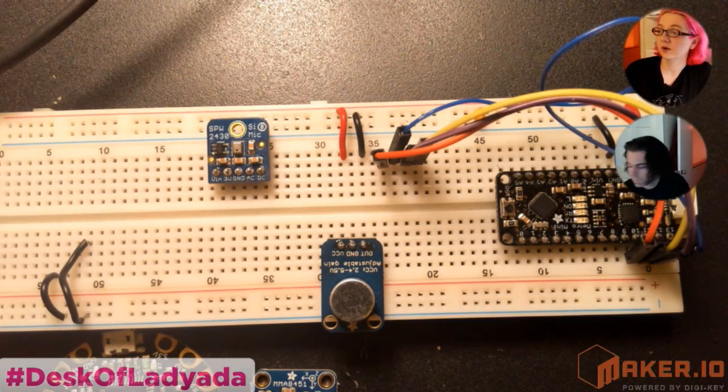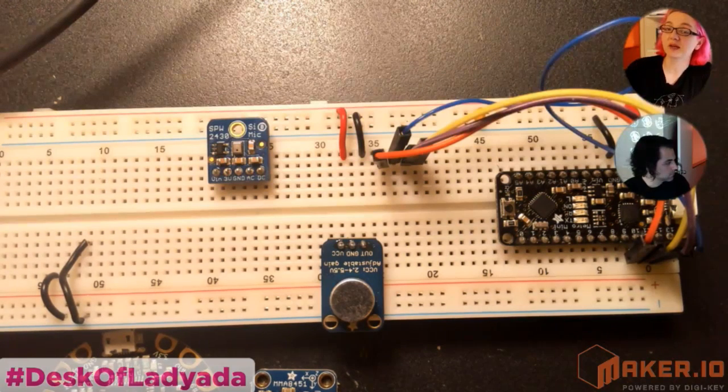Like the Nordic only has one UART bootloader. There's an over-the-air bootloader, so those are their two options. With the ESP8266, the bootloader is built into ROM. You're stuck with that. With the Atmega 324, you can use an Arduino-compatible bootloader, or you could possibly use a Moteino bootloader. As I played with it, I wasn't as happy with that, so I ended up sticking with the Arduino compatibility. But we'll talk about that also more in the prototyping and field testing.